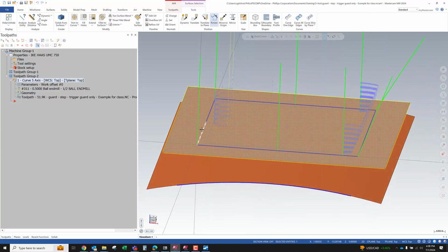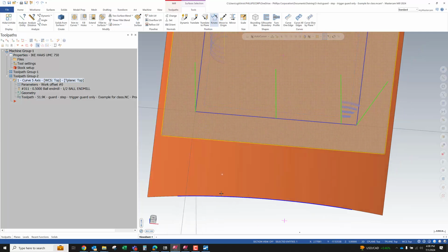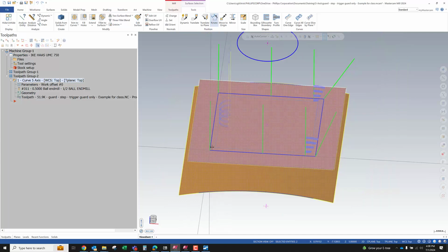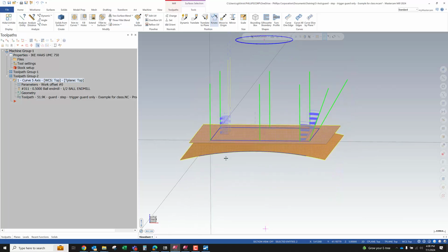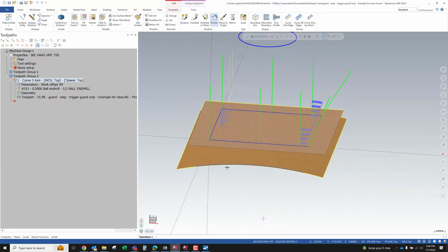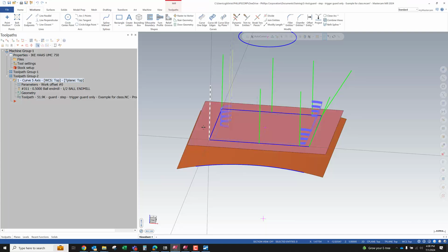I've got the geometry I'm trying to drive. I don't want my surface geometry exactly on the edge of the geometry I'm driving with curve. I want it to go way past. I don't want my normal surface to be right on the edge there. I do that to make sure that however the geometry is being projected down, I know the projection is going to lay there, because the dirty secret here is that the projection is done after the offset.